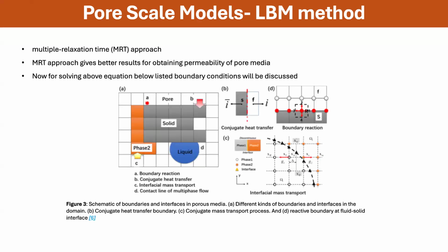Now to solve this method, there are different approaches that we can use. One is single relaxation time, and the other is the multiple relaxation time approach. We are going to discuss the multiple relaxation time, or MRT, approach because it gives a better result for permeability. Permeability is independent of the fluid that is being discussed. In single relaxation time, there is a limitation that it depends on the viscosity of the fluid being examined, whereas in the MRT approach it is independent of that, and that is what we want to focus on.